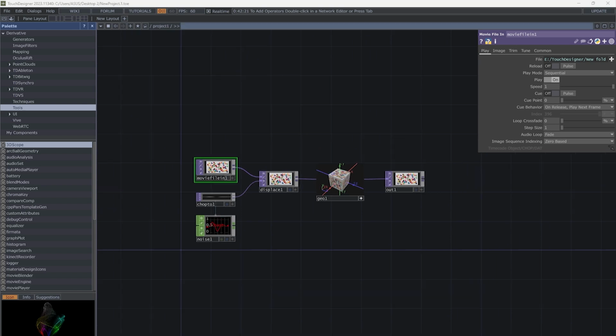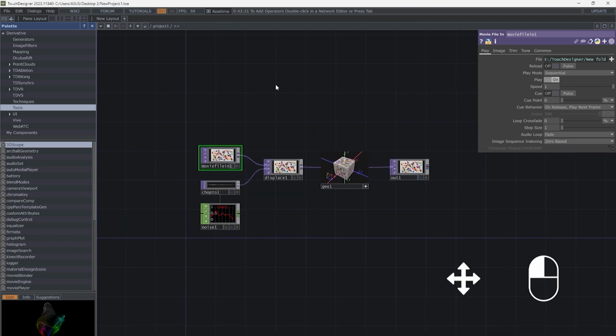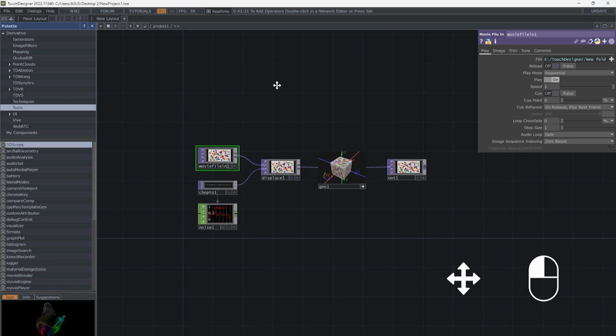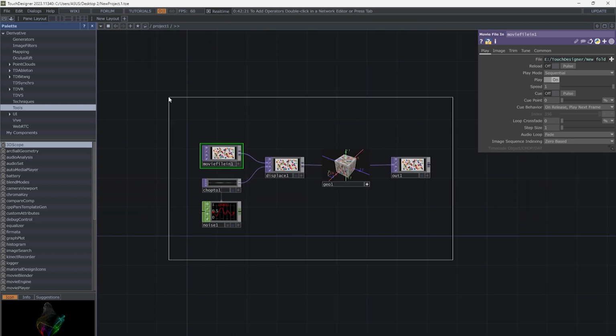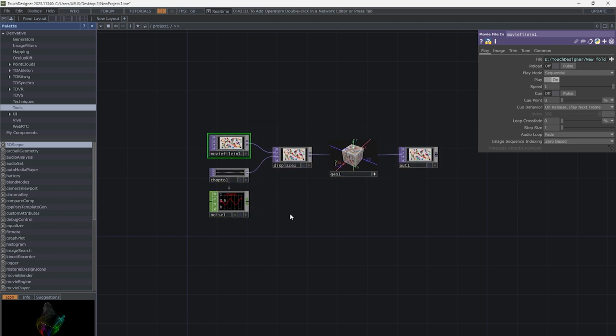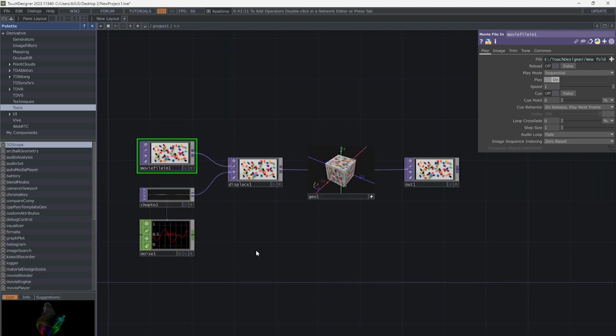There are some main parts in TouchDesigner, and I will explain them in this episode. You can easily hold left-click and move the mouse to navigate in the network window. Zoom in and out with the mouse wheel. By holding right-click you can select several operators. These rectangles are called operators. You can move them, delete them or add one.